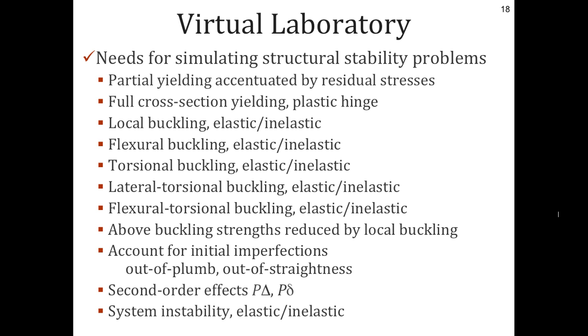Now MASTAN can do most of these, but it cannot do the local buckling ones. And so there's a few on this slide, I think two that relate to local buckling that it can't do. And so maybe there are more sophisticated programs out there, and if you want to study the impact of local buckling on the performance of a structure or on a member, you may need to dig a little bit further than MASTAN.